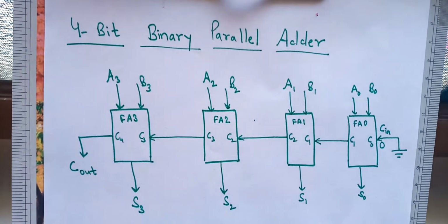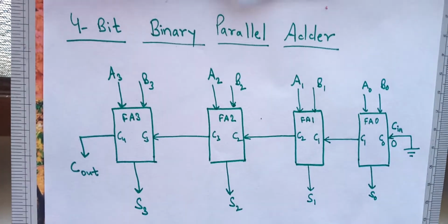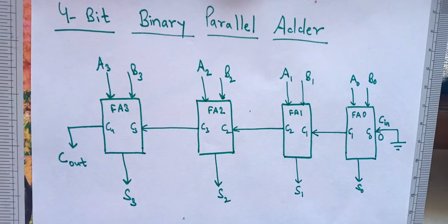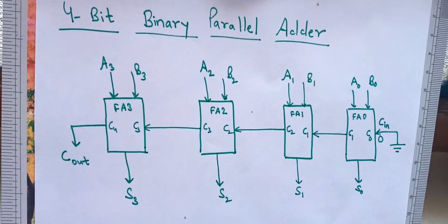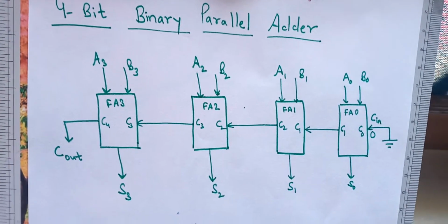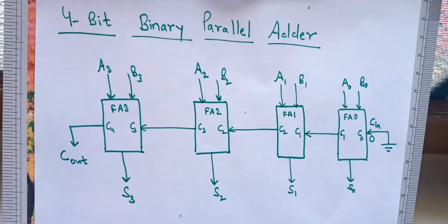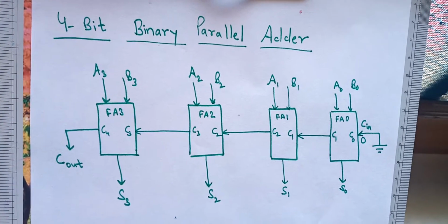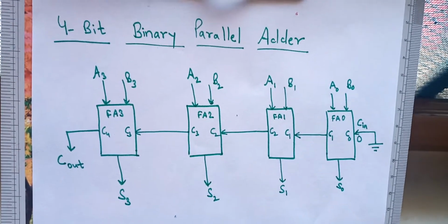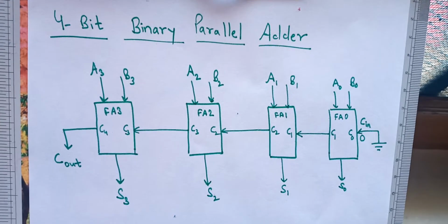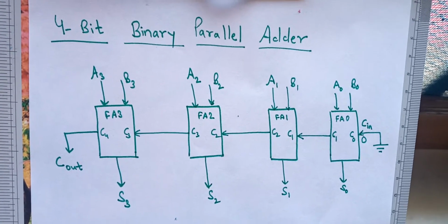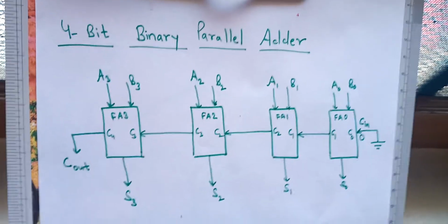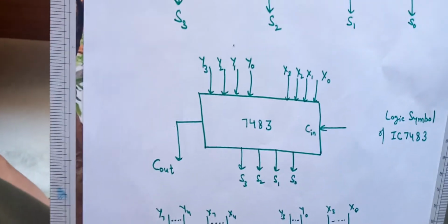Now this we have designed using 4 full adders, and this we can design and implement in laboratory also. We require 4 full adder ICs. We have inbuilt ICs of full adders, so those 4 full adder ICs can be utilized, and the connections can be performed in this manner.